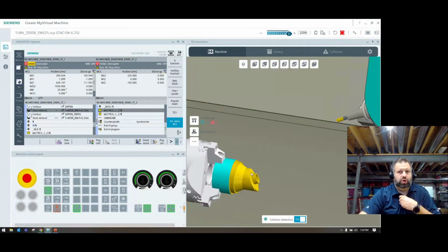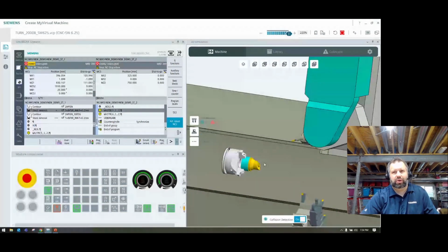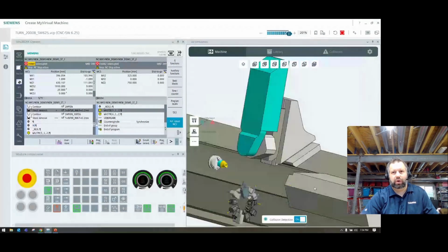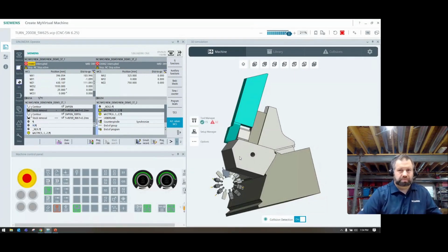This way I can just use a groove tool and groove in my gasket ring or o-ring. And I think that's really what it comes down to. And two, a lot of times when we talk about that, we're not looking at a part like that. We're looking at a huge part like this. You could never tool change in a boring head to do that type of groove or bore. That's why you're doing big interpolation turning on a big diameter part or a big hub in a big type of machine.